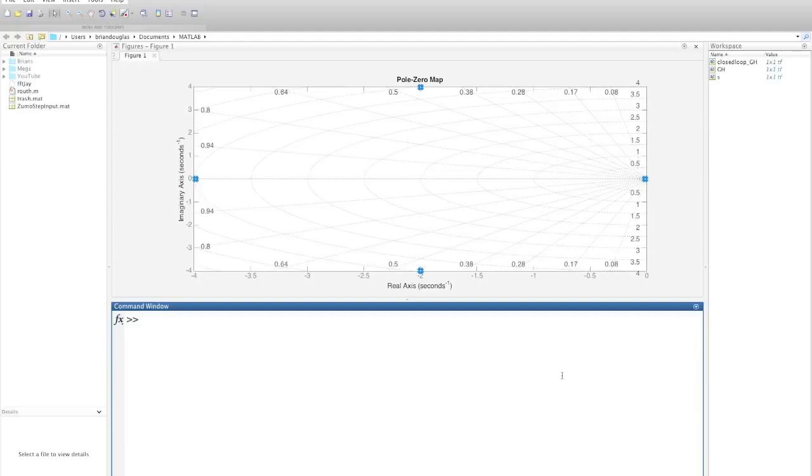And we can use this function to also plot the poles and zeros for the closed loop transfer function. This requires using the function feedback. To show you how to use feedback, let's write a really small script to plot the PZ map for the closed loop system as we sweep the gain from 0 to 10. I'll write a for loop to cycle through the gains. Now I want to use PZ map on the closed loop system for each of those gains.